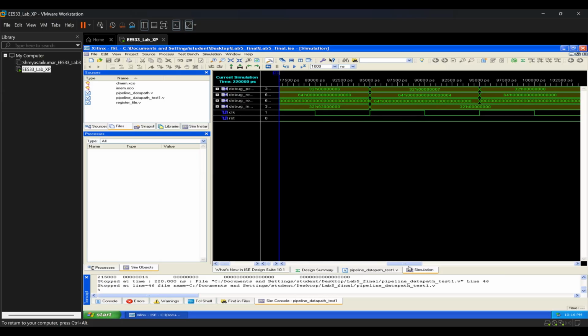In the middle, it's just a bunch of no-ops. And in the start too, it's loading address 0. Register 0 is equal to 0. So basically, it is also going to be 0 only into the respective registers. So I'm going to go backwards now. So as you can see here, clock cycle 7, 4. 4 is being correctly loaded. Everything happens on a clock by clock basis. PC is getting incremented.